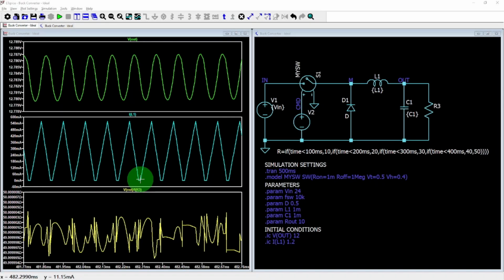In continuous conduction mode, or CCM, the inductor current flows continuously throughout the switching cycle, even during the off time. We've seen this in our first video on the buck converter. But when the load gets light enough, the inductor current may hit zero and stay there until the next cycle begins. That's discontinuous conduction mode, or DCM. A third interval is introduced where the inductor is fully discharged and there's no current flowing in the power stage. It's not a fault, it's just a different operating mode, and it's quite common at low load.